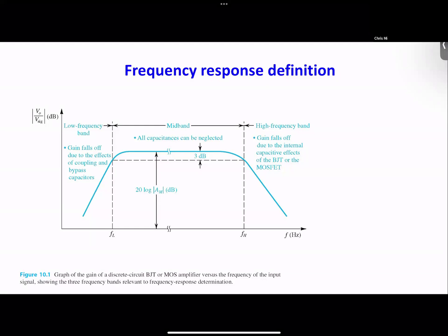But if you move out of your band, or if you move close even to the cutoff, like here, you're gonna say, oh my God, my performance starts to decrease, and we'll see why. But these areas here, we call this one the low cutoff, the high cutoff, okay? And the drop is defined as 3 dB.